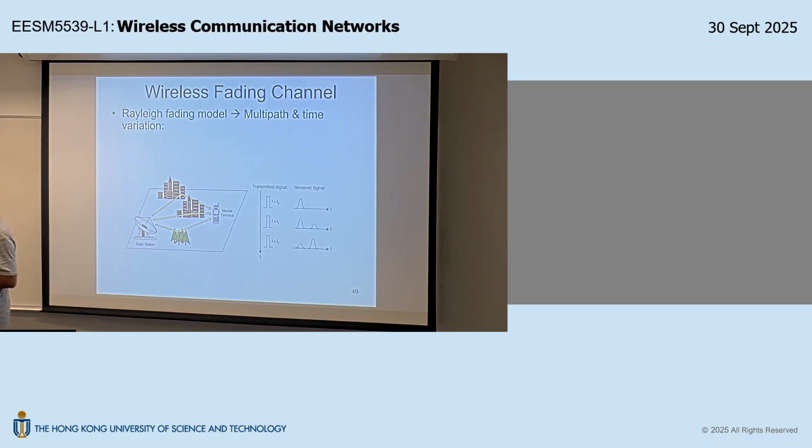It depends on how severe the multipath is. It can go from 2 to 4 or even beyond 4. Now, if this is 4, what does that mean? If I double my distance separation from the transmitter, my receive power will be reduced by 16 times. So the higher the path loss exponent, the faster the receive power drops with respect to distance.